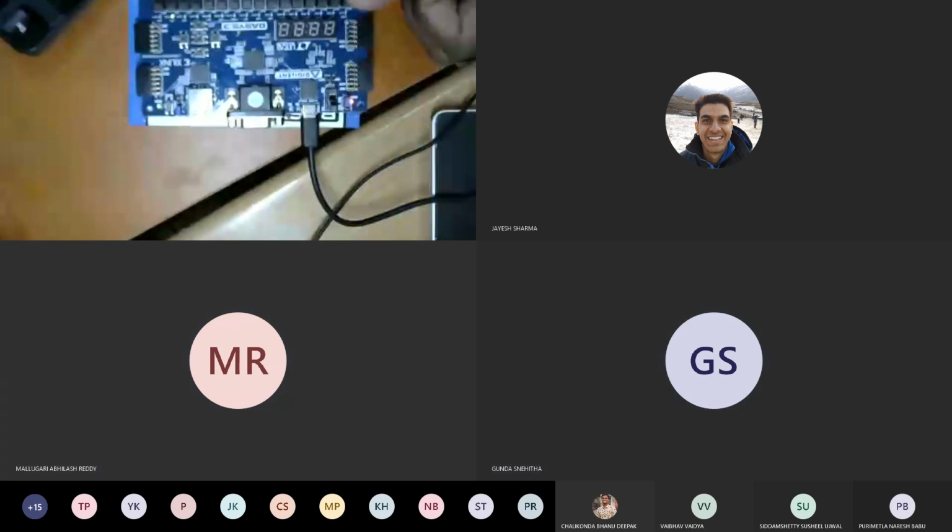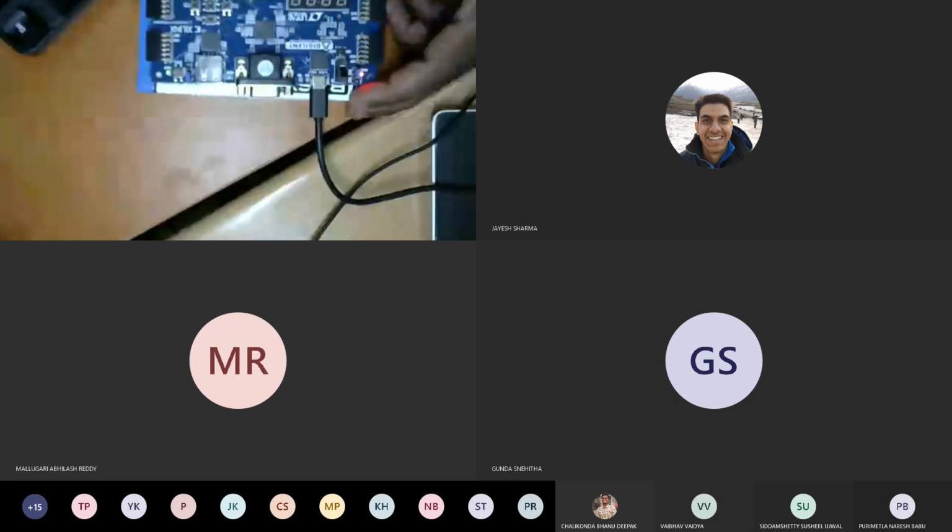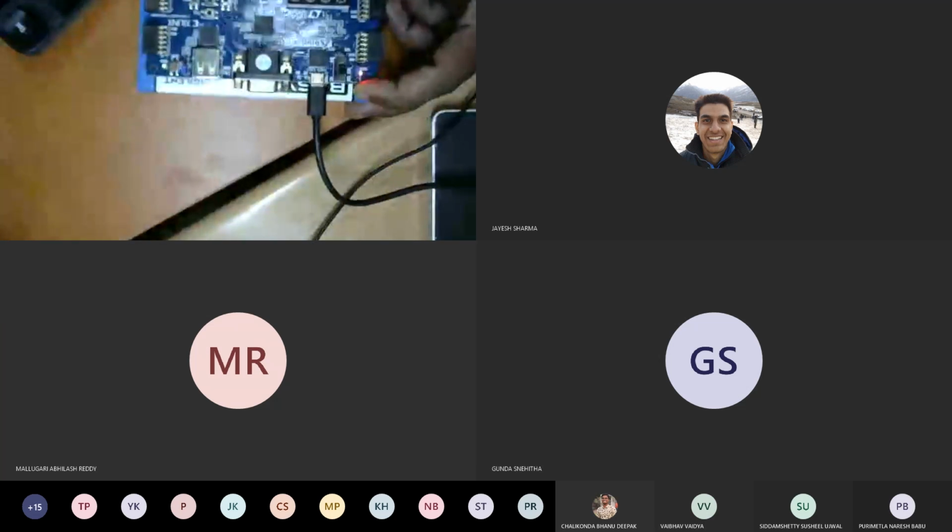Now if you see what I did, I think, if I remember correctly, in this JK flip flop, J I mapped to the first switch, and K I mapped to the second switch, and the third switch is reset now. Generally, with the D flip-flop, the second switch was the reset, and the third switch is my reset now. Again the clock is on the central button, and Q is here and Q bar is here.